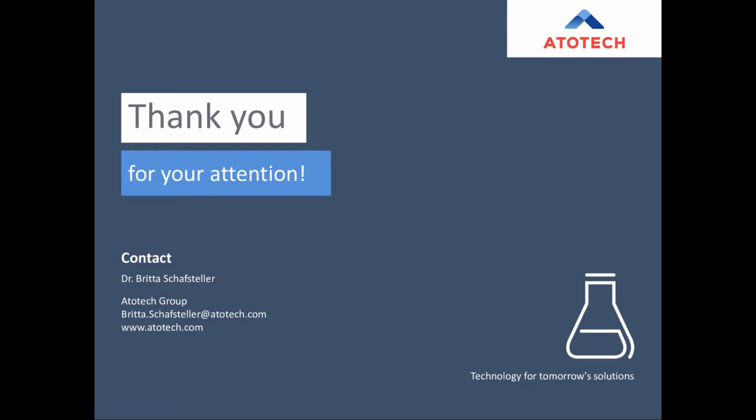Everything which is not level 1 or level 3 and which is not perfect is a level 2. From these different levels, we collect all the levels for the 7 images of one PTH, and then we form a kind of mean judgment for the one PTH and say, okay, if we have no corrosion, then it's a rating of 0.